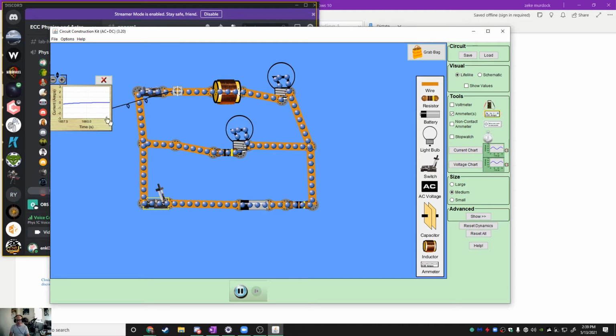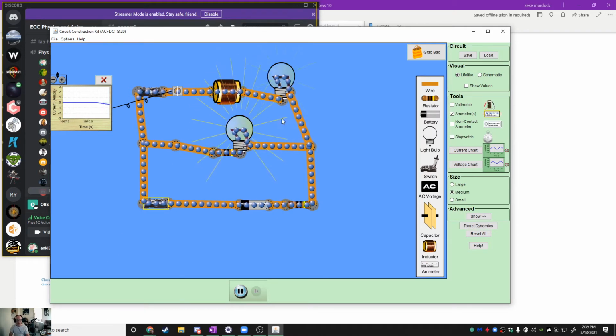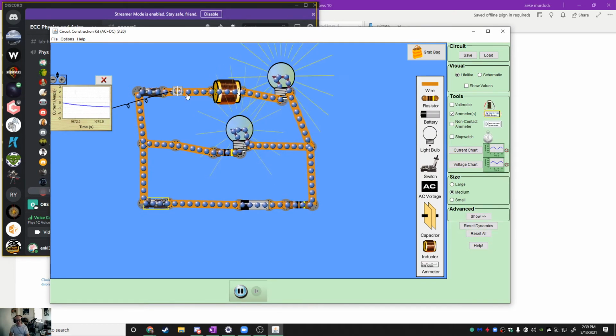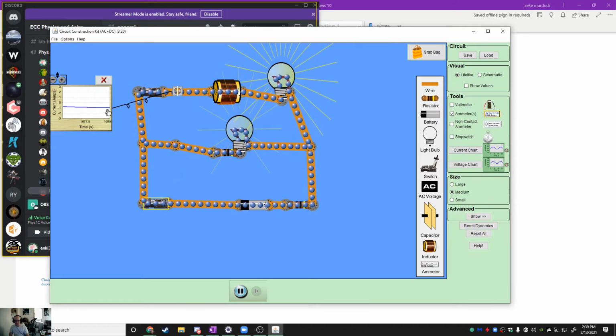When you turn the circuit on, you're going from zero current to something, which means that the inductor is going to say, well, you can't just instantly do that. So it's going to set up a reverse EMF, okay? And you can't see it on here. The only way you can see it is just that these electrons in the top here are flowing a little more slowly. Okay. Now, when we open the circuit, it's reached maximum, right?